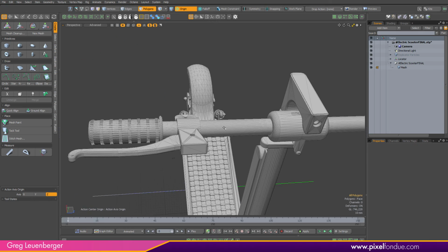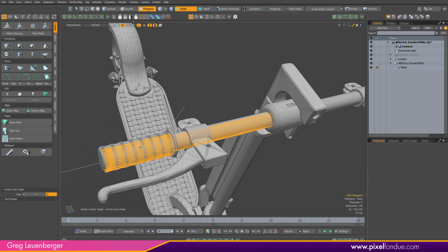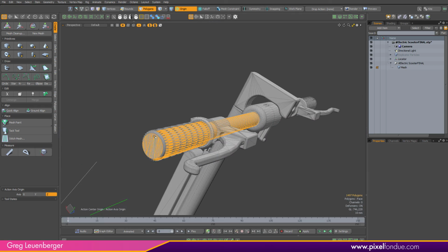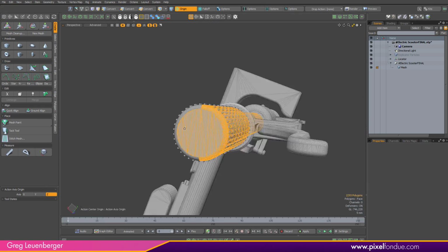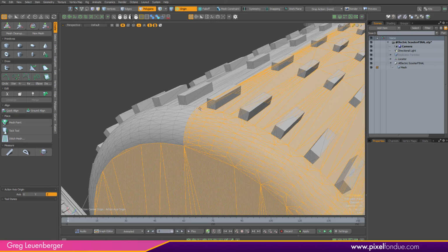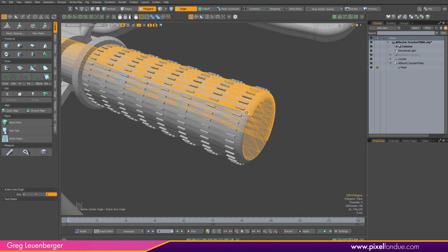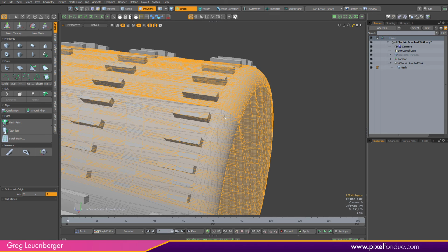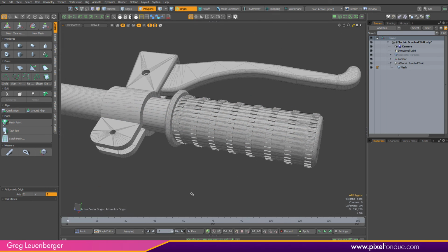So, you may want to try go in and just double click polys like this. But you'll notice this isn't quite working, right? So I'm only getting, these aren't connected, like the vertices are not fused. And this is pretty typical with CAD files that you bring in. And these surfaces are all separate. But we might get lucky with parts. Remember, parts come in as well.